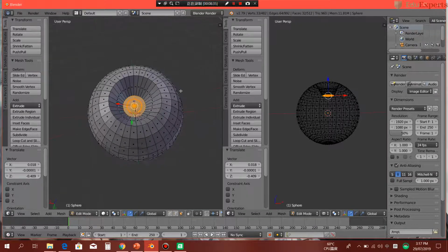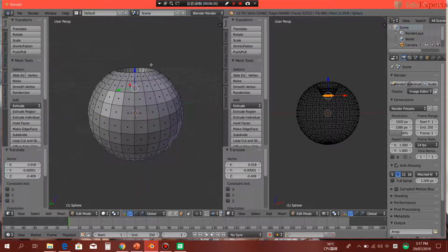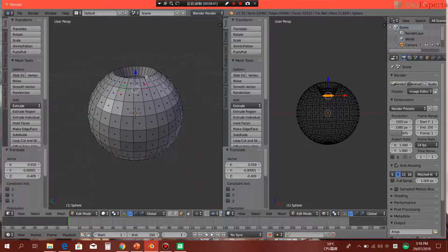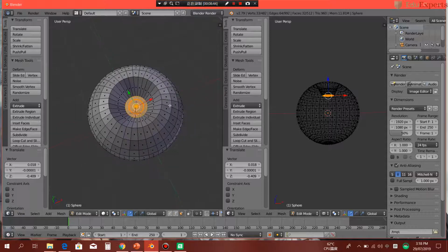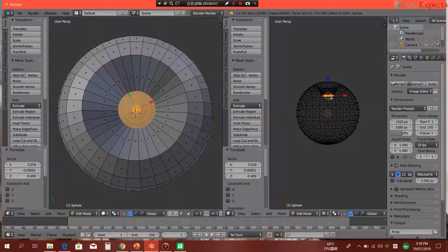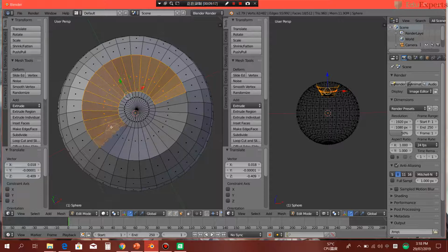Even if we got that, it still doesn't look like an apple. The top edge is a little bit too sharp. Fixing that is just one step. Next thing I'll do first is cancel this selecting area. Press C key, middle mouse button, gone. Then I quit the select mode. I'm going back to the left window, and now I want to select this outer area. So again, press C button, and I'm going to adjust this circle size to make sure I select the correct path.